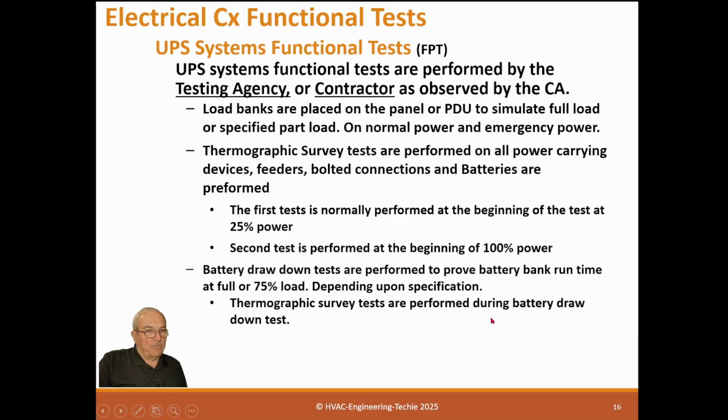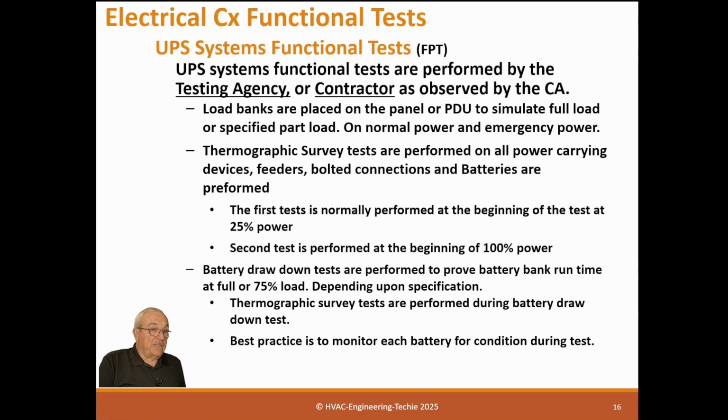Thermographic survey tests are performed during battery drawdown test. Best practice is to monitor each battery for conditioning during the test. So if your testing agency has the capability and equipment for this, they actually wire a testing connection to every single battery, and it tests incoming and outgoing power, and it tests the temperature of the battery. So it actually has a temperature probe and has current tracing available and voltage tracing on the battery.